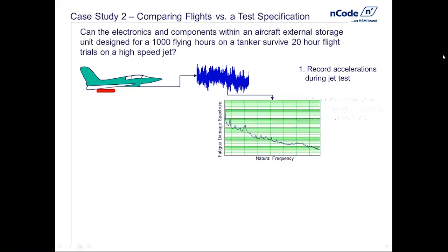So we can see here then, we'll calculate this thing called the fatigue damage spectrum. And we'll look at this in more detail in just a minute. This is like a frequency spectrum, but now the vertical axis is in fatigue damage, or severity of accumulated cycles, plotted versus frequency. So this allows us to understand how severe the mission is.